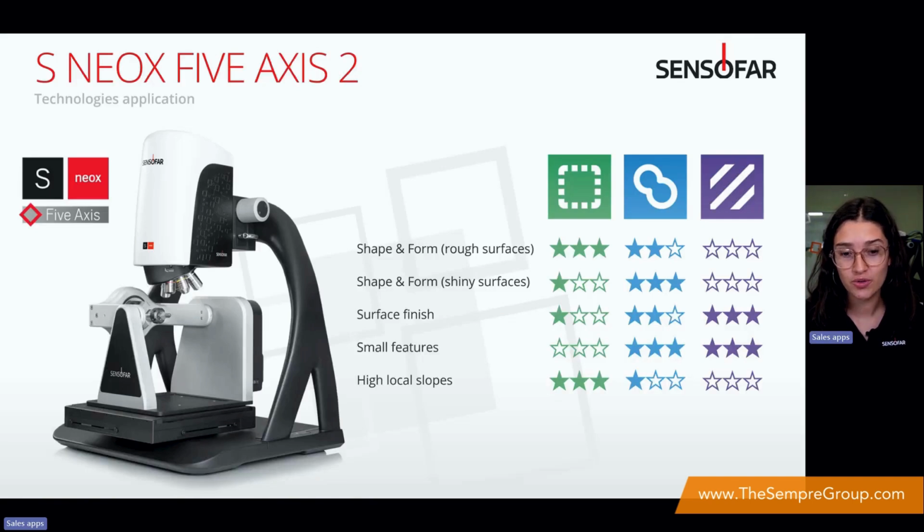The system that I want to talk about in more detail today is the neox 5-axis. As I told you before, this system has 3 different technologies embedded in the sensor head. First of all, we have the focus variation technique here in green. With this technique, we can measure really good shape and form of rough surfaces and big samples. It's also really useful to characterize high local slopes, and it is the fastest among the 3 of them.